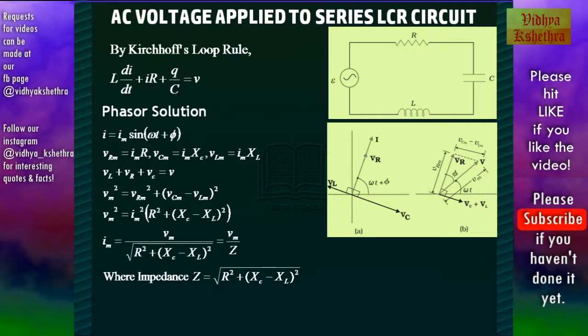Therefore, Im is equal to Vm by root of R square plus (XC minus XL) the whole square. That's equal to Vm by Z. Here Z is known as the impedance of the LCR circuit and is given by root of R square plus (XC minus XL) the whole square.